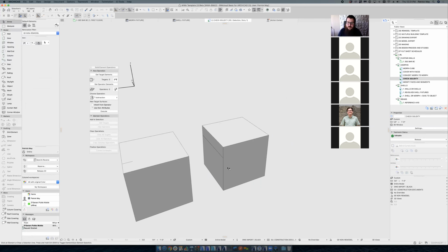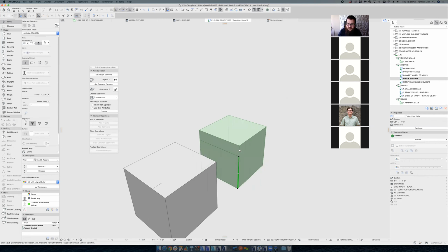The other thing about the morph is a lot of times you end up with stuff like this and you go, oh, well, I want to get rid of these two pieces. And sometimes deleting those will delete the whole morph. I don't have a good reason on why that does that, and it's a real pain to try and track that down. Again, the workaround is to basically grab these edges and track them around and get rid of it this way, if you end up with segments that are deleting the whole morph. Got it.